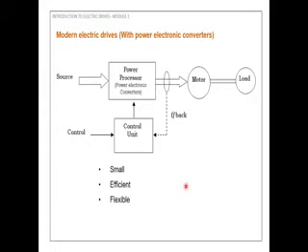For example, we preferred a DC motor, and the output of the power electronic converter is connected to the motor. The source voltage is AC, as normally the available voltage is AC. So the power electronic converter block is a rectifier, which converts the AC voltage into DC. This DC voltage is given to the DC motor, and the motor rotates.